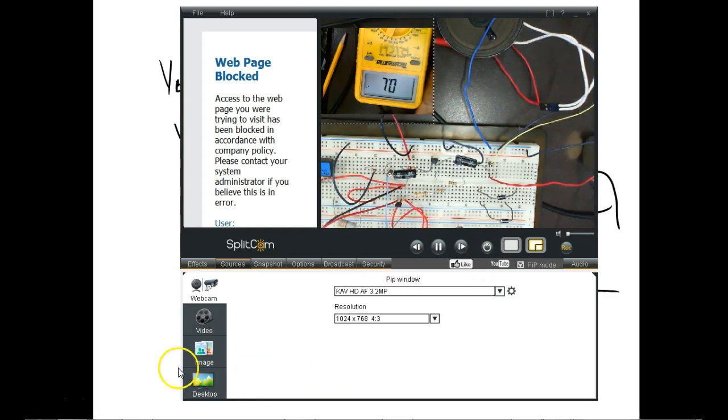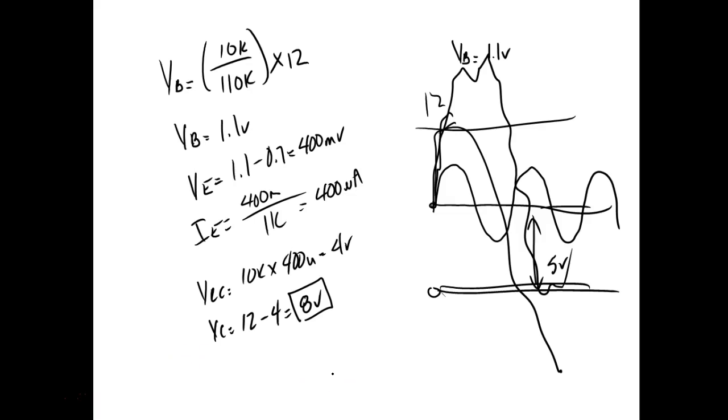Now, y'all understand, if it checks good in circuit, we assume it's good, right? You understand? If it checks bad in circuit, what do we do? We isolate it. We raise one lead. We unsolder one of the leads and raise it up, right? You understand? And we check it out of circuit. You don't have to pull it completely out of circuit. You just need to isolate one of your leads. That makes sense?